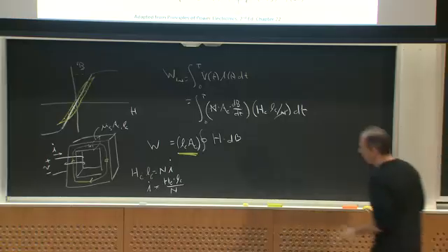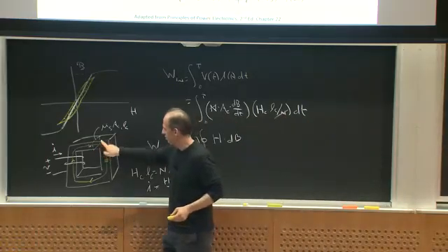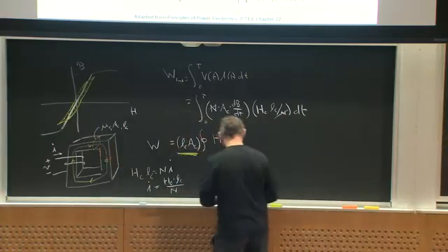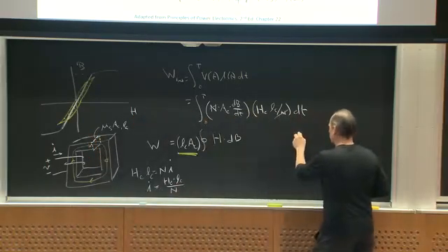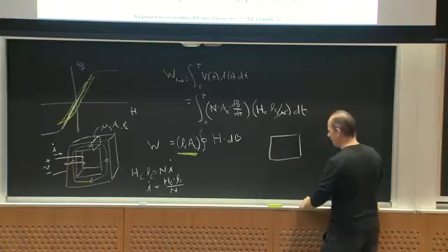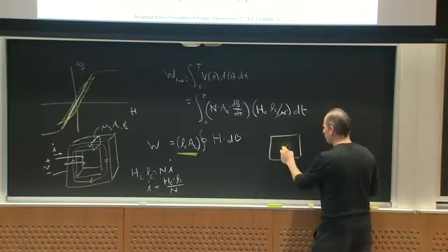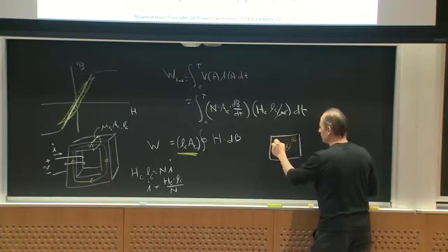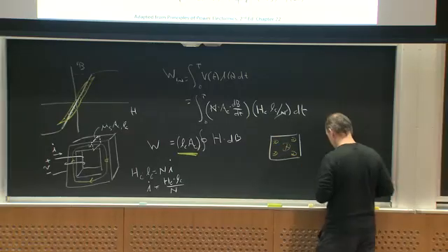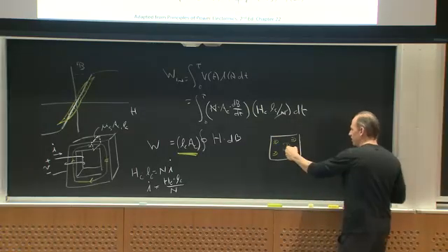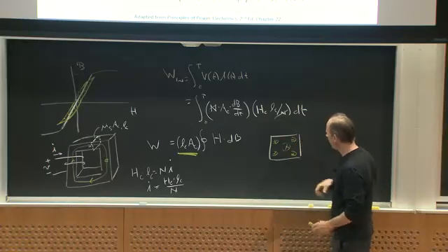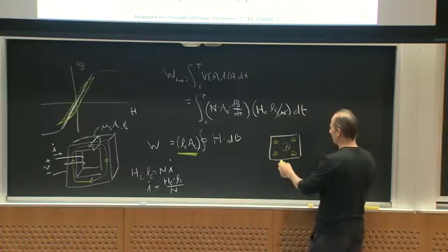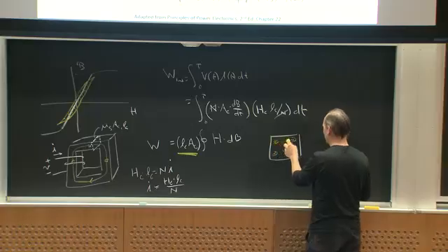And so if I looked at this cross section, that I drew here in white, what I would get is I would have some flux going in like this, right? And what would that do? If I have an AC flux, dB/dt, I'm going to generate a field inside the conductor that does this.